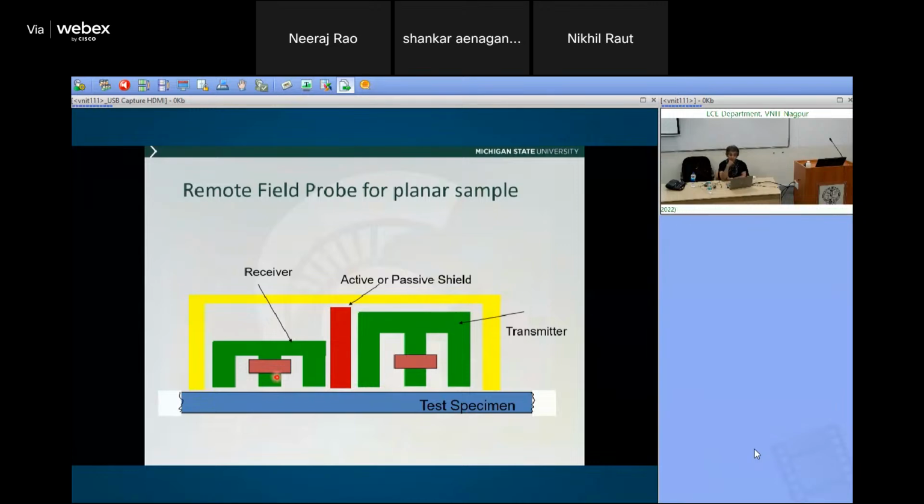So when you want to detect defects in very thick steel, like a petrol storage tank, this was actually used for detecting corrosion where you have a really thick piece. They could use eddy current with this kind of setup for detecting corrosion on the outside, deep inside the steel floor of the tanks. So that's the advantage of the remote field.